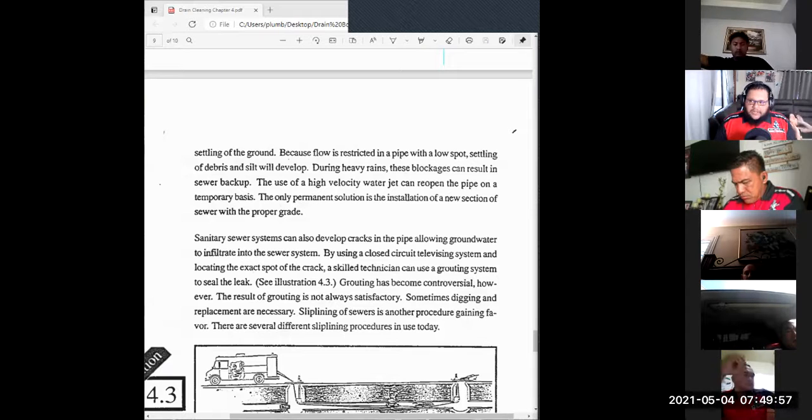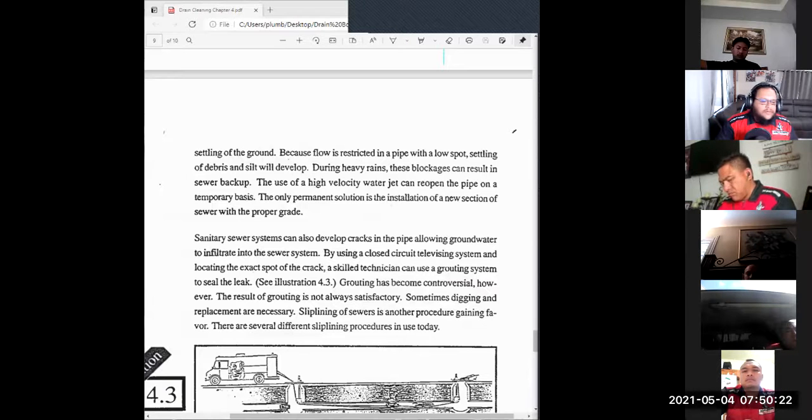You said that everybody knows, Josh, but does everybody know? That is a question. Because I'll tell you, when you have a 20-foot length of ABS or PVC, and let's just say it's hanging on a rafter or stored on your vehicle, and you take it to a job site, a lot of times there's this thing in it called a crown, and it's how the pipe sags over time and over length if it's not supported properly.